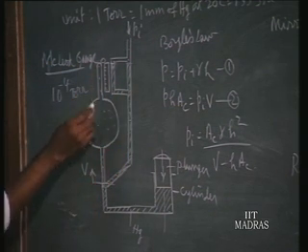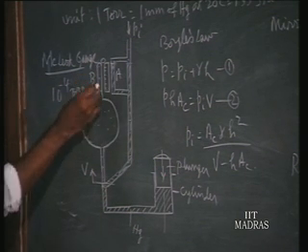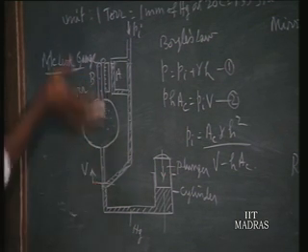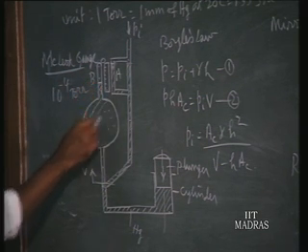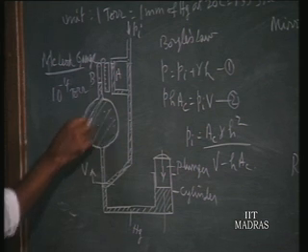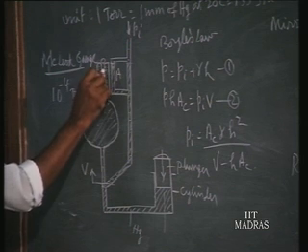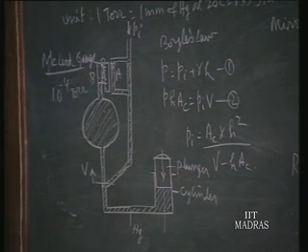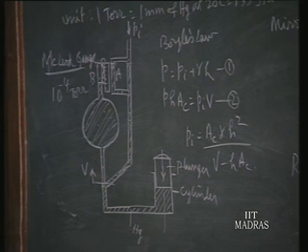Until it reaches, at that time you will find, suppose this is capillary A and this is capillary B. In capillary B, this full volume V is given. The manufacturer will give you what the volume is. The mercury may come up to here, occupying the full volume. Now take this height. We call it the measurement height. That is what you are supposed to measure after making the mercury column come to 0 level: find the height of the compressed gas column in capillary B.